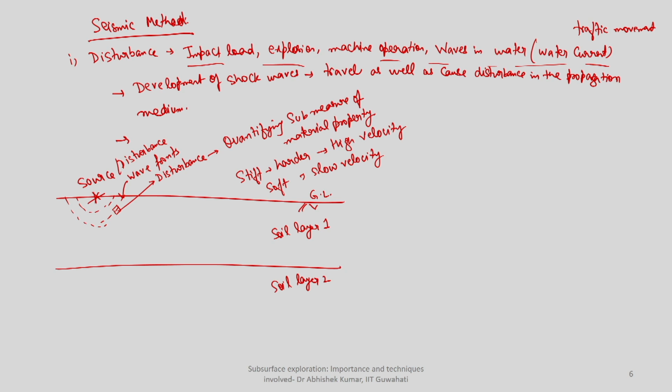Now, when we went for trenching, test pits, and geotechnical tests, we were interested in finding out what kind of soil layers are there and what the strength properties are. Even here, our target will be to determine the thickness and some measure of the physical properties of this particular soil layer.